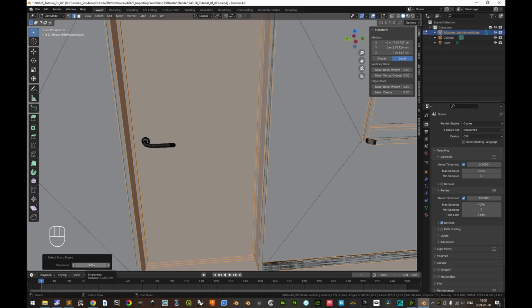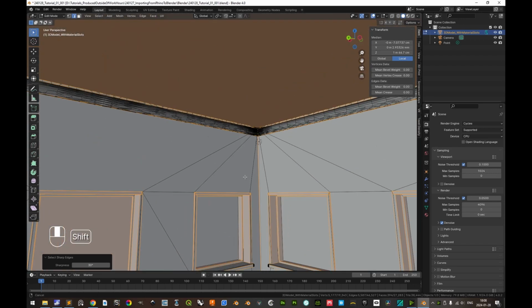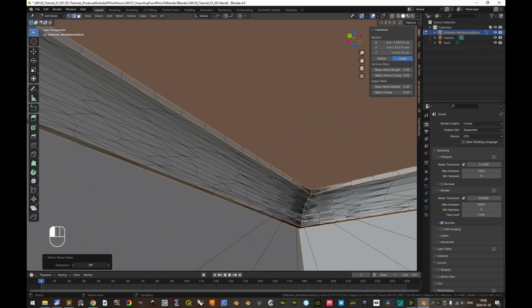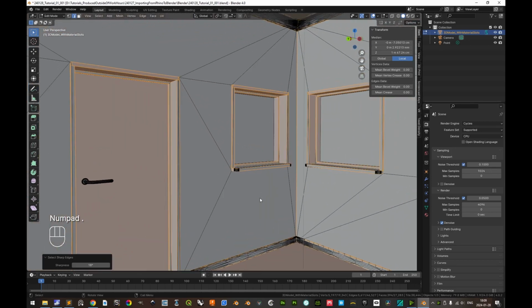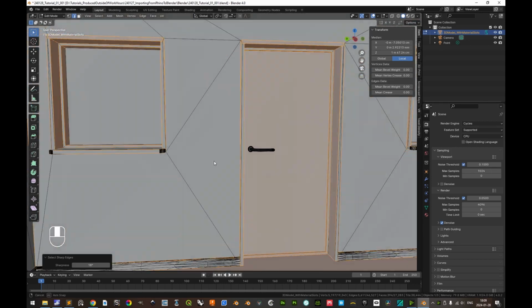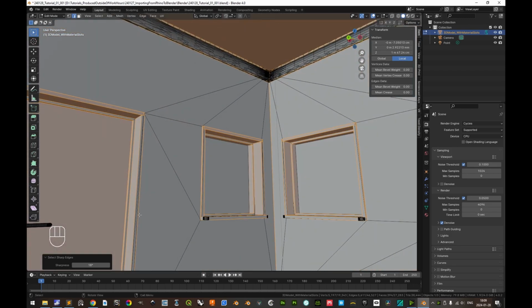You can experiment with this so that it is good for your particular geometry. Perhaps 18 degrees might be good, so as to make sure that this whole curve is interpreted as sharp. Let's see here, period comma to escape. Let's see if that created something bad in any other way here. Yeah, that's good. So in this case, we did 18 instead of 30, but 30 might be better in your